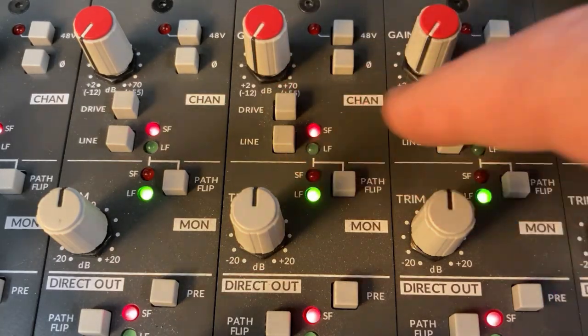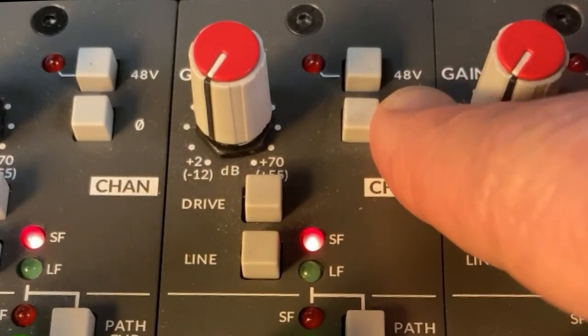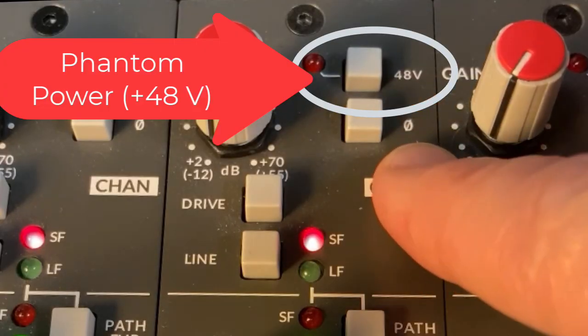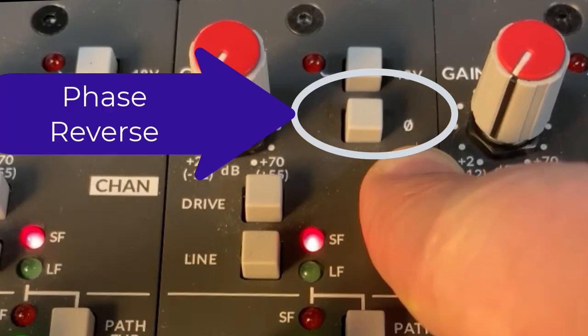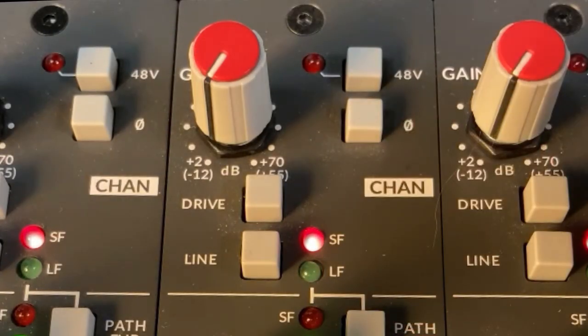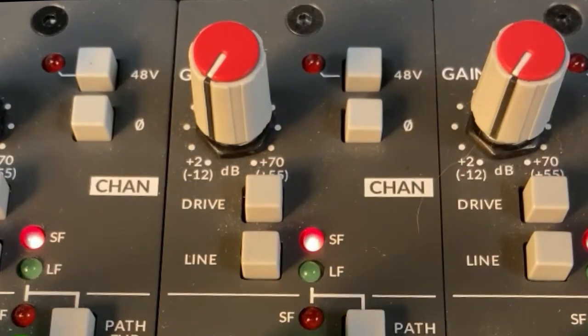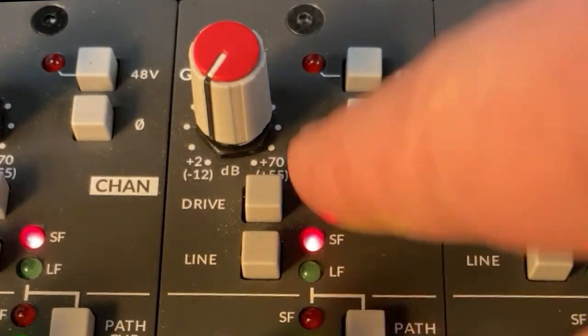So in your channel input section, we have a couple of different buttons here. We have the 48 volts, which allows us to supply phantom power to our microphones if we need it. We have this button that has a null next to it, which is a phase flip, which you need sometimes, particularly when you're miking the bottom of a snare drum. So we have drive and line. If you're using an external preamp, you'd use line, but most of the time we don't want to press any buttons here unless we're using 48 volts.